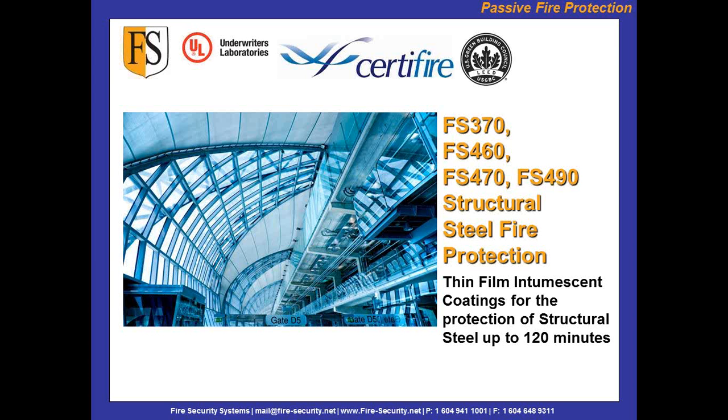You can have high build or thick film coatings. A lot of the epoxies for hydrocarbon applications are high build. They can be up to half an inch to 3/4 of an inch in thickness. They can still be intumescent too and expand, but they expand for a greater rate of a fire curve or a higher fire of around 1100 degrees Celsius.